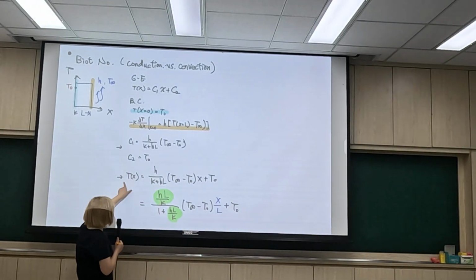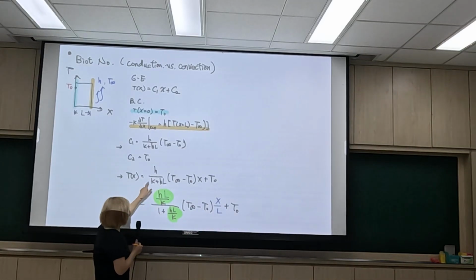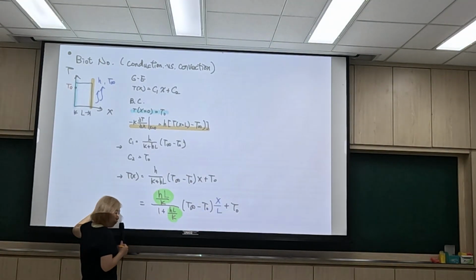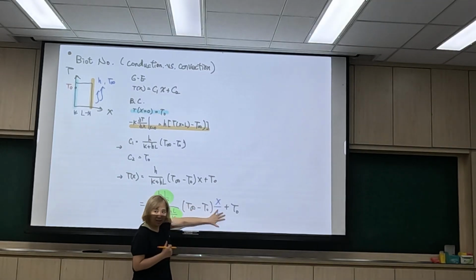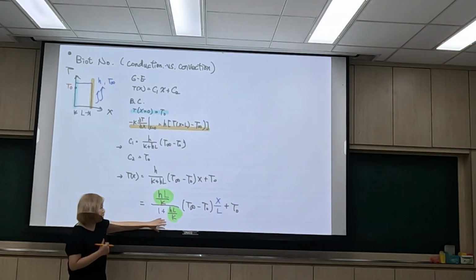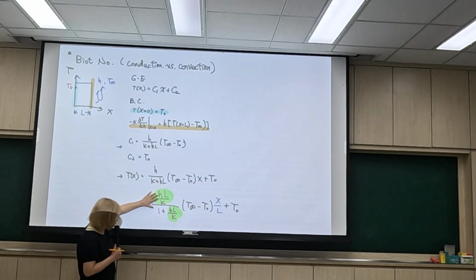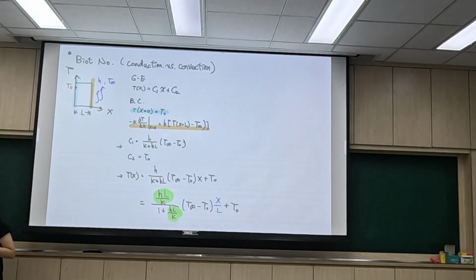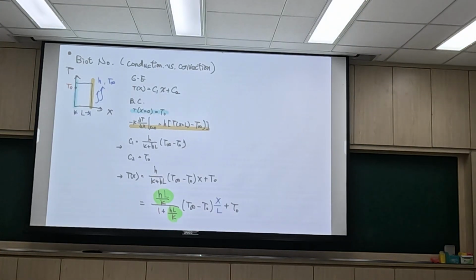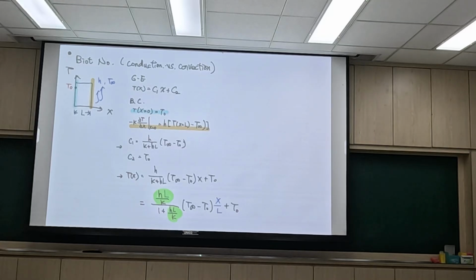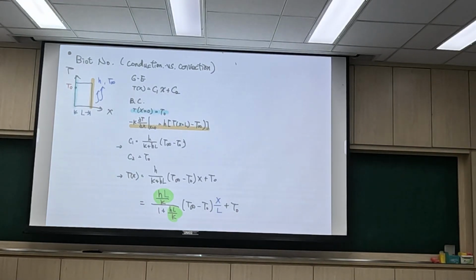If you put T(x) minus T(L) and divide, this term will be the temperature difference, and this will be the size difference. And there is a function that expresses that using this kind of term. So this is very important, and this is the one we're going to introduce today, the Biot number. Let me write it down in red.